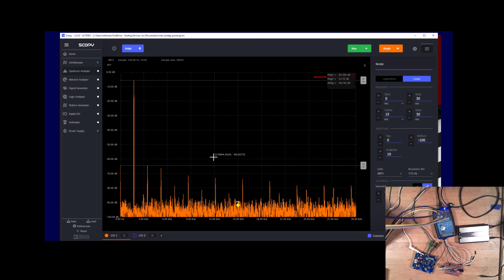We do have second harmonic present, so asymmetrical clipping, but it's considerably farther down than with that Schottky diode. Here our delta is about 58 dB, so again, about 0.1% distortion. We were getting a little bit better earlier, but we are approaching the limits of the ADALM2000.